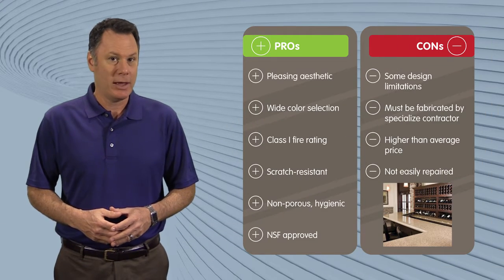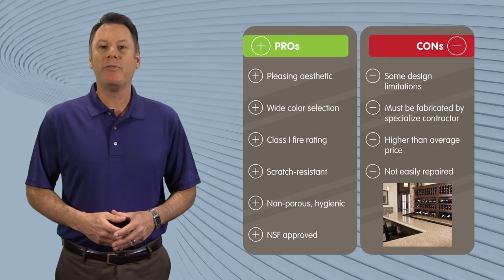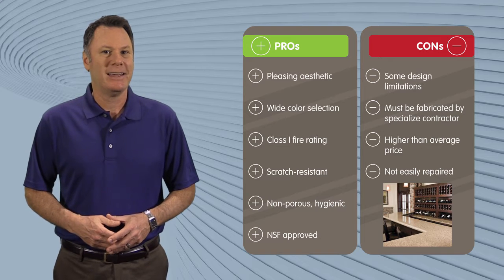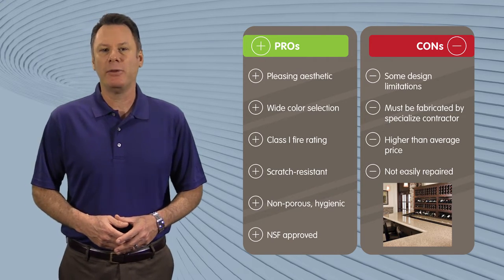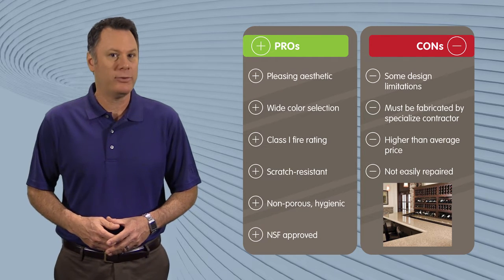Pros include pleasing aesthetics, wide color selection, Class 1 fire rating, scratch resistant, non-porous, hygienic, and it's NSF approved. Cons: some design limitation, must be fabricated by specialized contractor, price, not easily repaired.